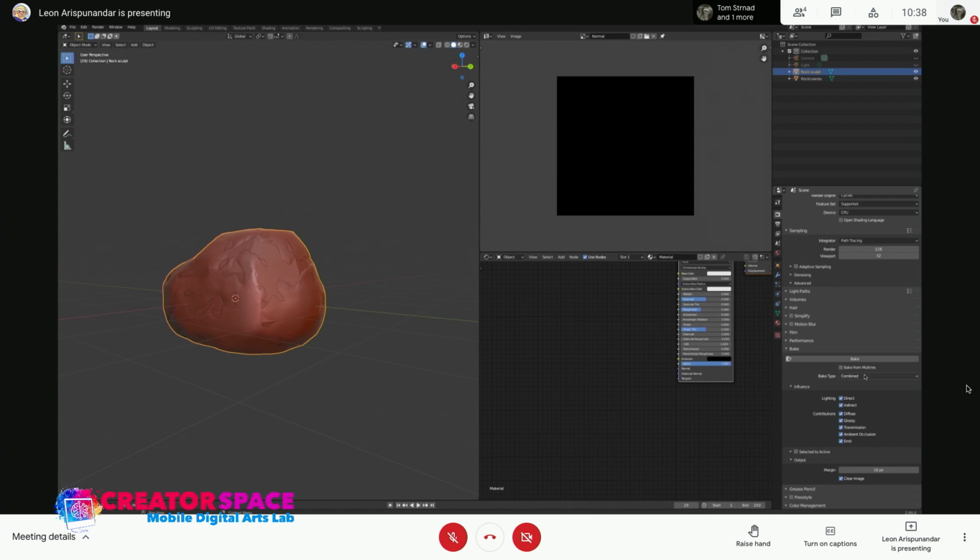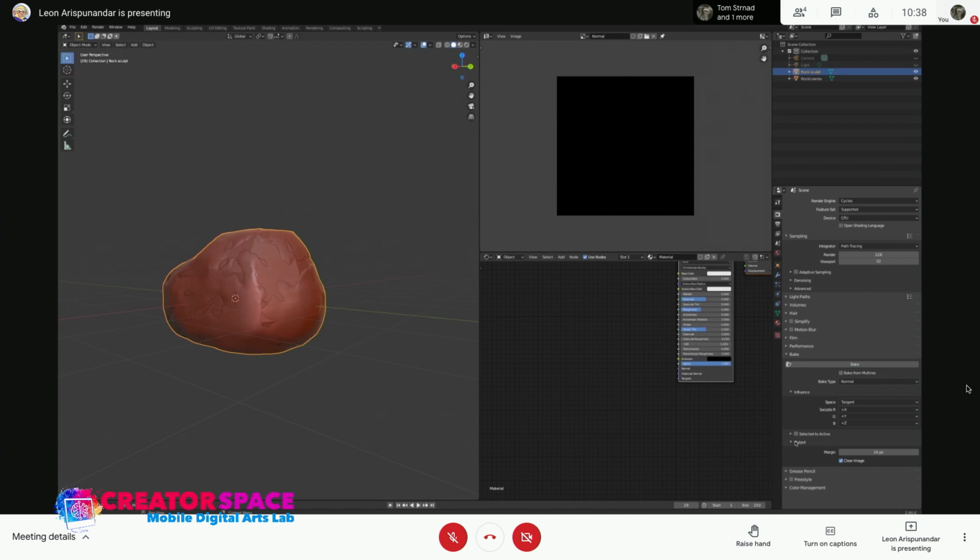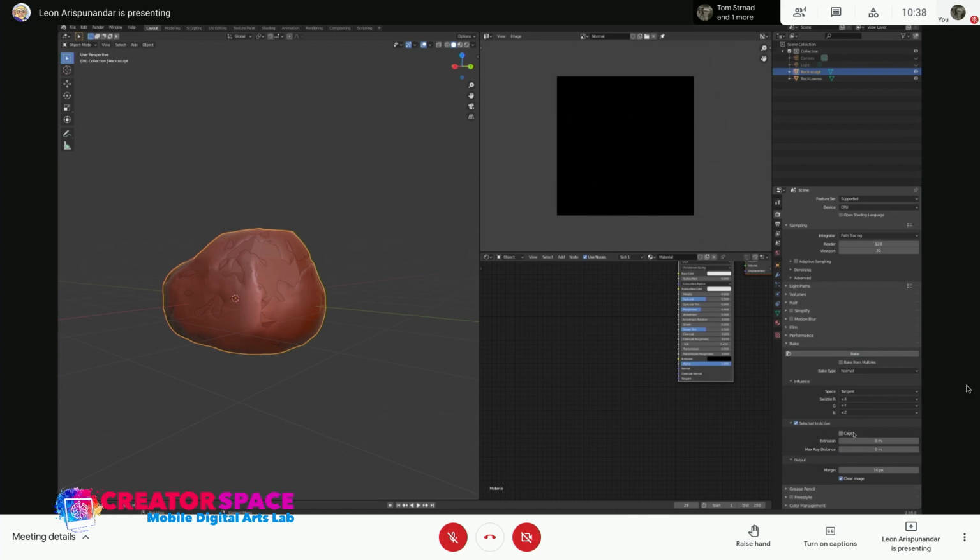If you open that, right now the type is combined. So we want to click that and change that into normal. And we want to click the selected to active. And then the maximum ray distance is 1. The margin existing pixels, that's good. Everything else should be okay.